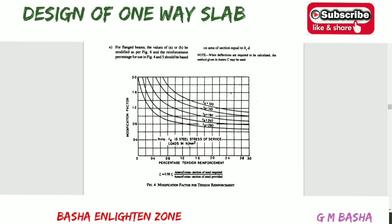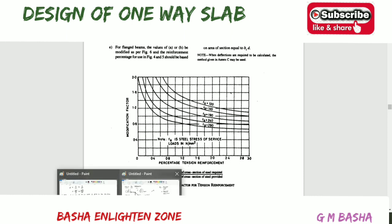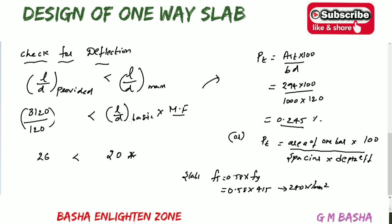So here I am considering the modification factor as 1.5. Maybe in other visuals you will get 1.6, small minor changes. If you relate the coincidence, you will get 1.5. If you simplify that, you will get 30, and here L by D will be less than 30. So almost all, we are satisfying each and every criterion step by step. Therefore, it will be safe.